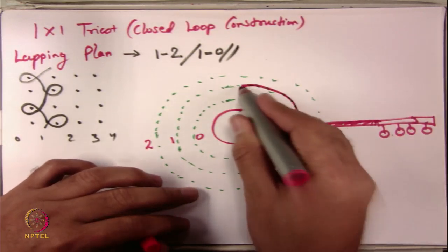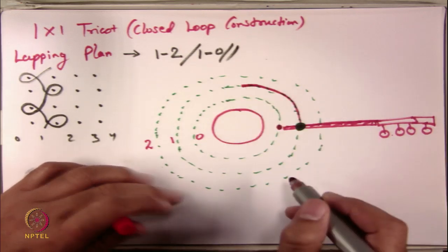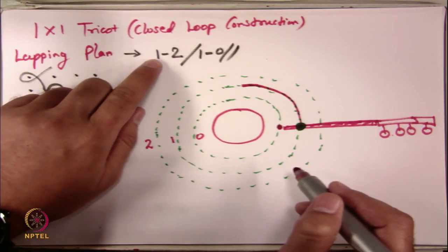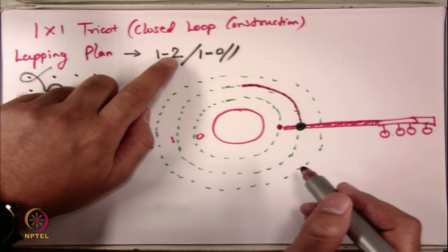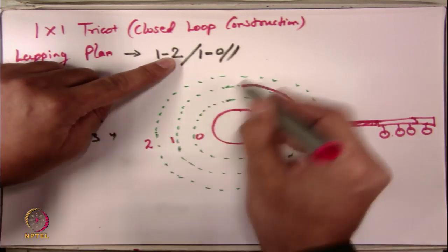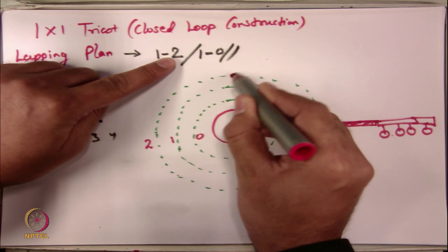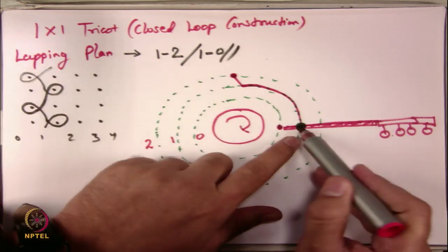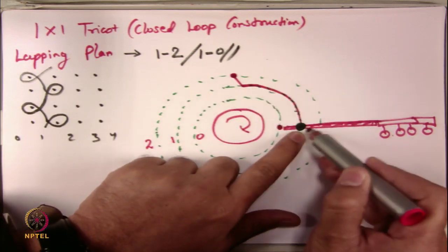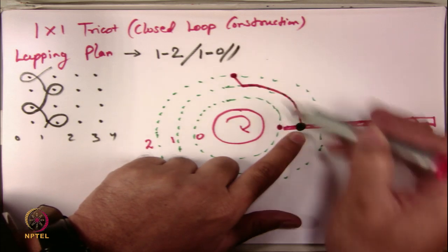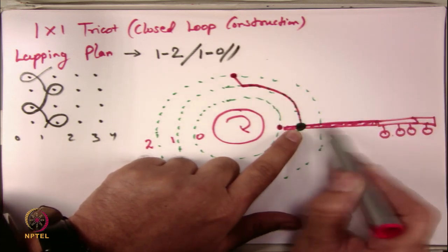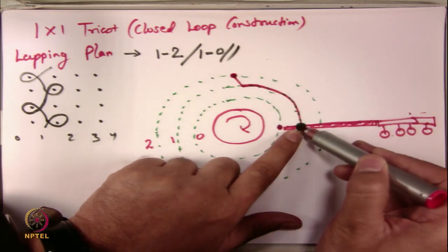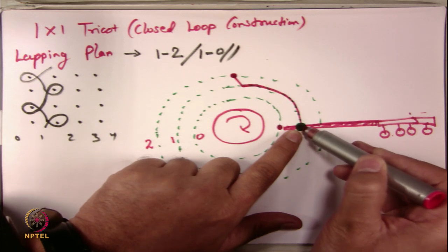Okay. So, it must be doing swinging to certain time. So, this is the swinging to go on the front side. From first, now it is moving to the second position. So, this is your second position, now it is shifting to this particular position. Once this is rotating, the follower will follow this part, and when this position is coming, suddenly the follower will be pushed towards right. So, it will move in right direction when this point is coming and interacting with the follower.